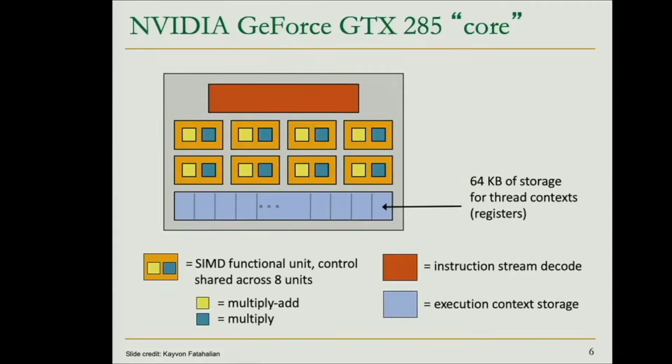Inside each of them we might have several processing elements or several ALUs, let's say. For example, we have something that is able to do multiply accumulate operations or multiply add operations that are very useful for linear algebra, for neural networks, for example. And we may also have other ones. We can have special units for integer computation, for floating point computation, and this is also something that has changed a little bit over time in the different designs of the GPU architectures. But essentially, the thing that we have inside one of these GPU cores is what you can see in the slide.